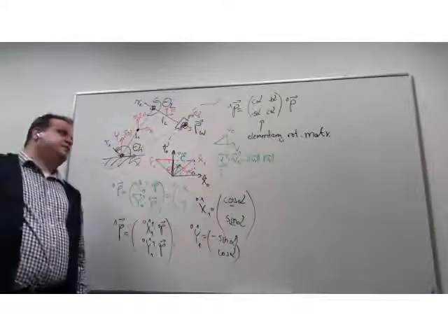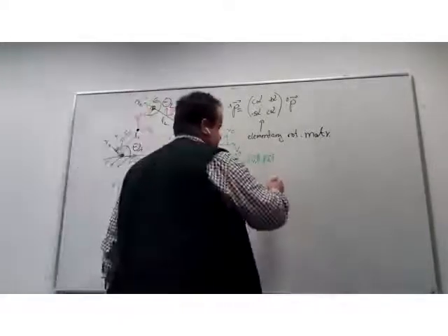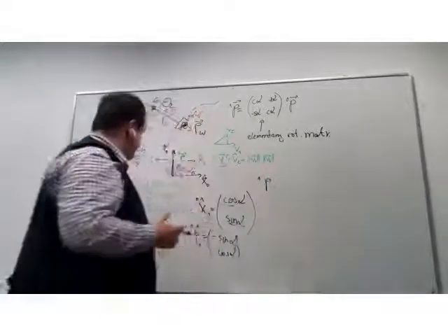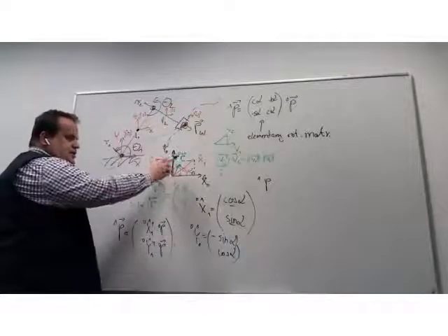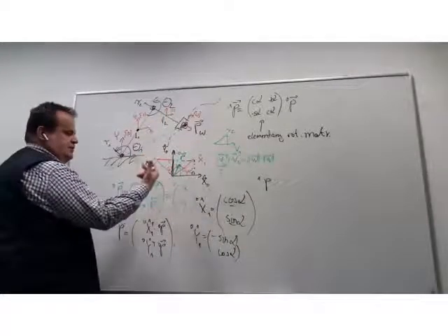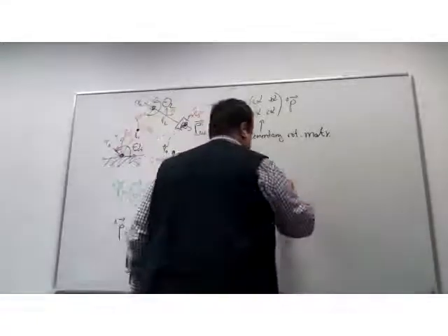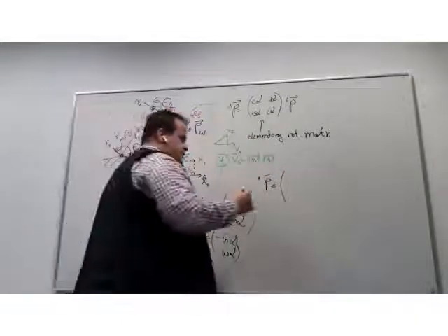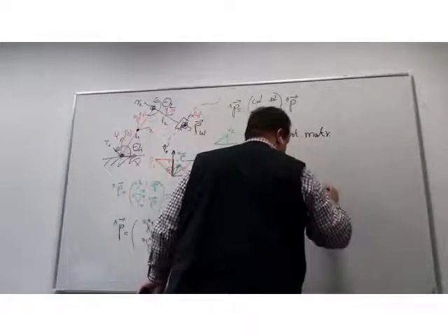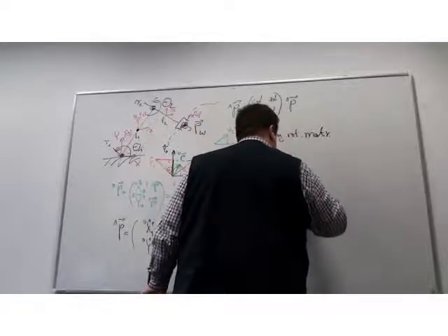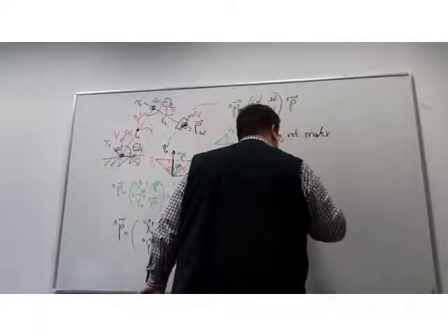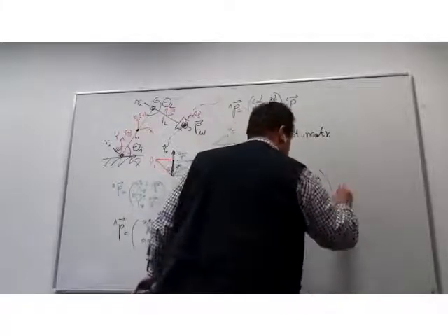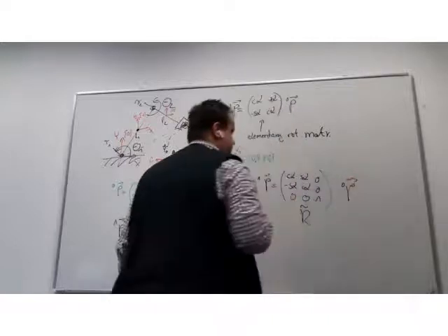By an angle. So we can write this matrix also as a 3D matrix. P1, we see that this matrix rotates around the axis sticking out of the board, around the Z. So the P1 matrix extended now to a 3D system will be 1, 0, 0; 0, cosine alpha, sine alpha; 0, minus sine alpha, cosine alpha, times P0.